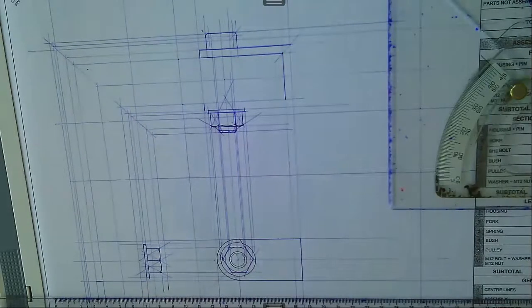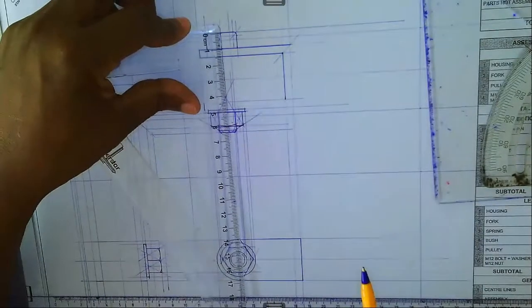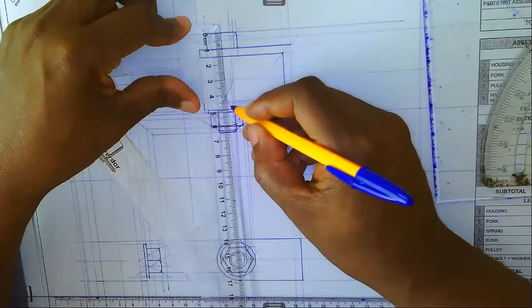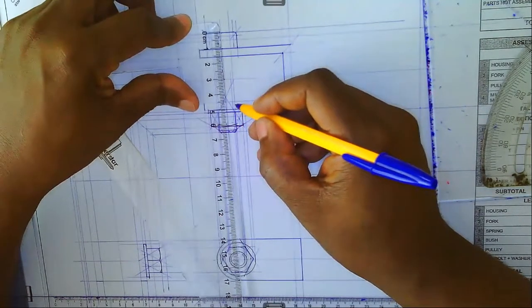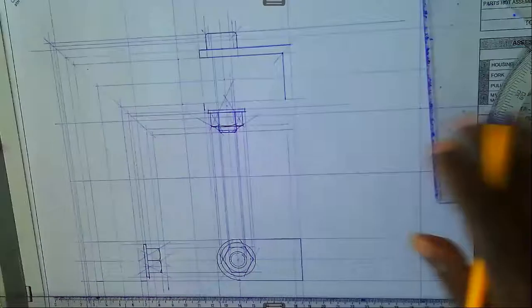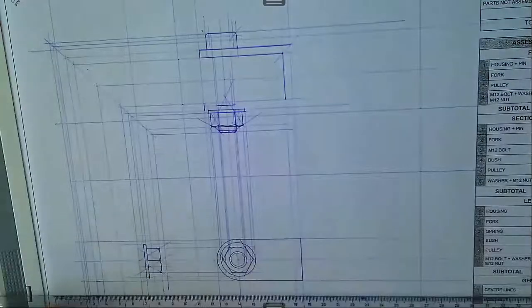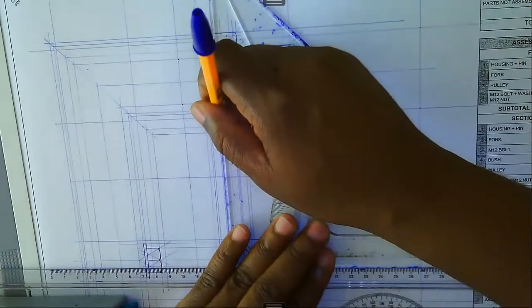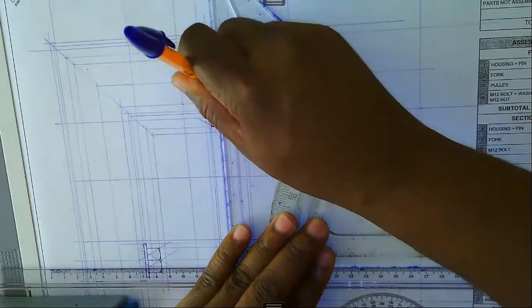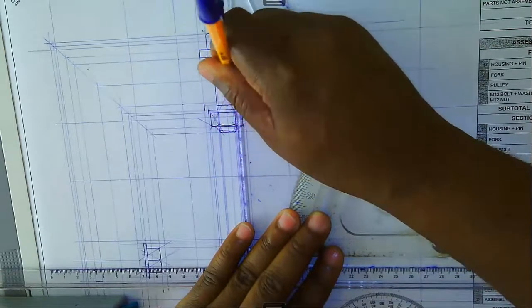Okay. What we also need to check is the thread length. From here to there, we need to measure 48. It's from the end, so we measure 48. 48 would be somewhere here. Let's align with the center line. It's exactly here. Then here we draw a line like that. Then we outline this. When you are ending a thread, make sure you outline that. But we take this one right to the center because that's where it is supposed to be. So we are going to do this. When we stop there, we are also going to do this. Then we stop there, okay?